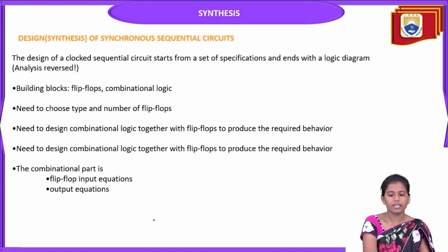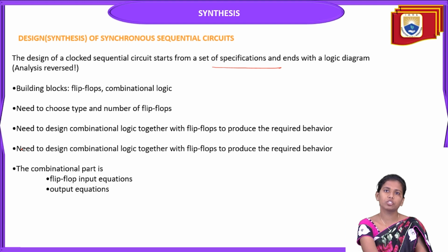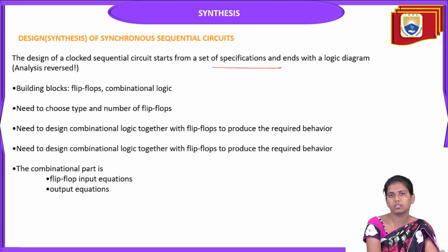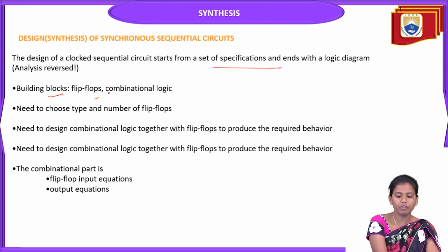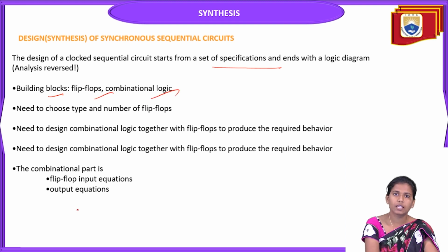And coming to the design, synthesis of synchronous sequential circuits: the design of a clocked sequential circuit starts with a specification and ends with a logic diagram. Here the sequential circuit consists of memory elements, right? So it starts with the specifications and ends with the logic diagram. The building blocks are flip-flops and combinational logic, so the synthesis can be done with respect to the flip-flops as well as the combinational logic.